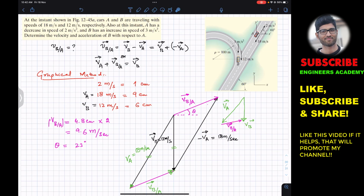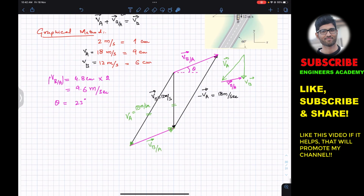And if you are required to find the velocity of A relative to B, we have to start a vector from the head of B, and that will end on the head of A. So again, we have that same VBA length, we will have that same answer, and that will be 9.6 meters per second. And if we measure the angle of this VBA, we will have that same angle of 23 degrees.